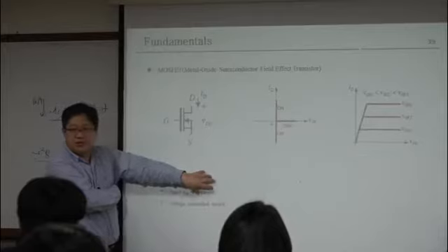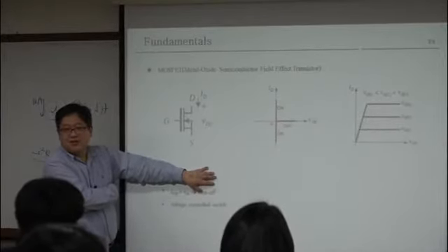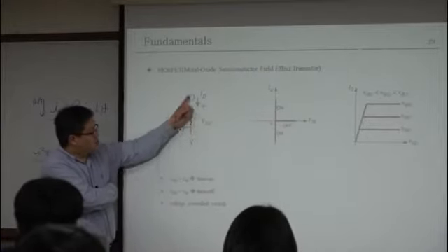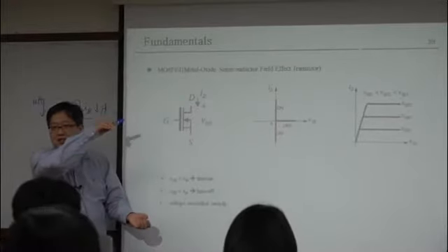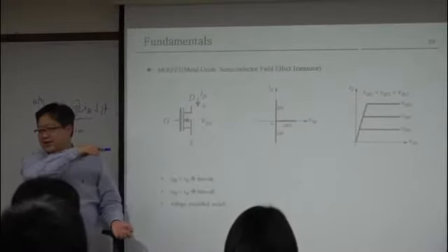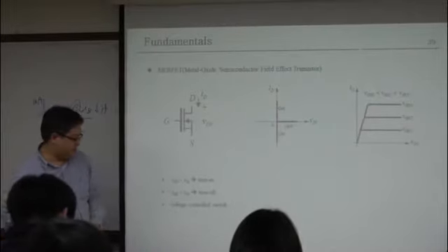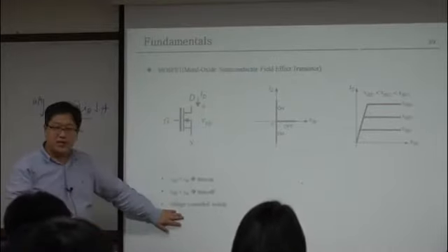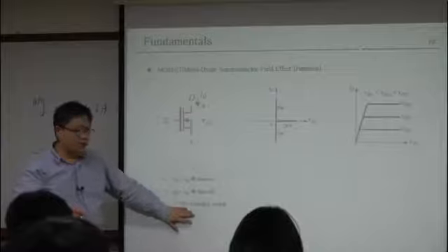But that is a simple logic. In reality, it's different. If you give higher voltage, then the turn-on characteristic is also different. But too high voltage also creates some bad effects. So in reality, it's a little bit different. Since it is only controlled by the gate voltage, this device can be called a voltage controlled switch.